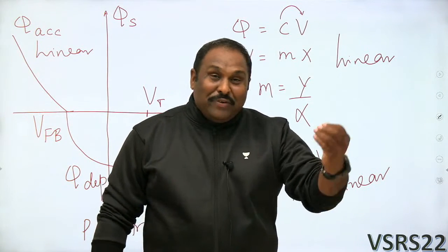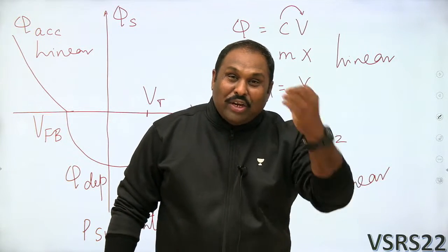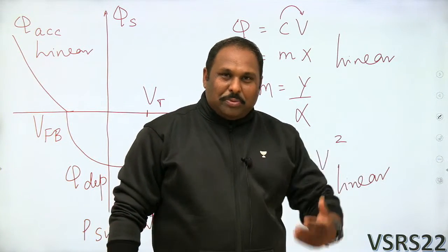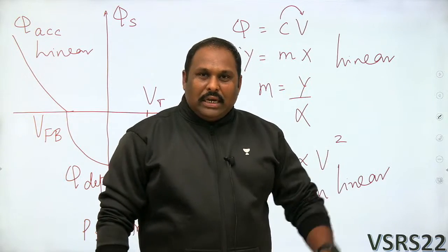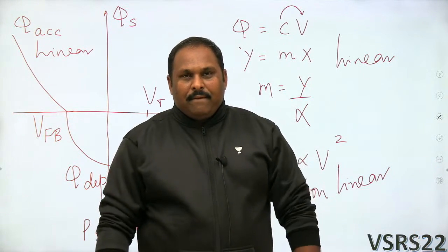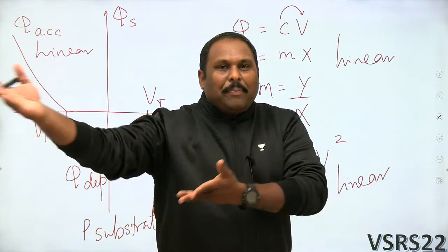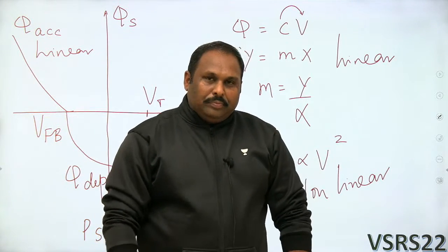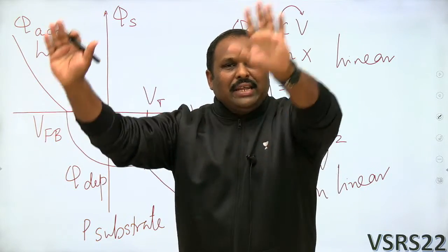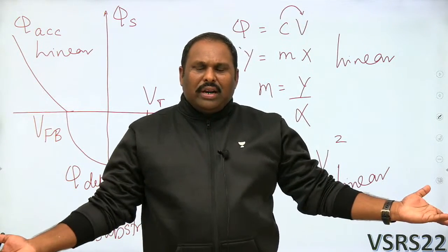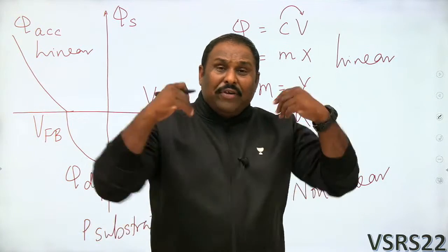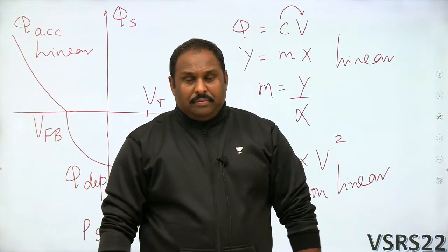The depletion region width is considerable and important only when you're doing the depletion mode of operation. Now textbooks, especially if you go to any standard textbook, they'll give you the depletion region formula even in inversion mode, which is of no use, because that calculation has no relevance in the capacitance calculation. There may be a depletion region, but that is almost filled up with the carriers. So there's no relevance for the depletion region calculation. So don't unwantedly learn formulas for every mode and confuse yourself.